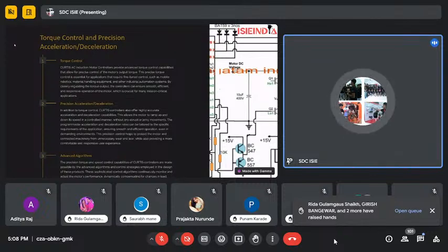Okay, so what is the first thing that comes up in EVs when we talk about how the controller operates? The major thing that comes to mind is VFD, variable frequency drives, which control the AC motors, and in that we move towards scalar or vector control. In vector we come to FOC or DTC, field oriented control, direct torque control, or somewhere we also move with PID controllers.